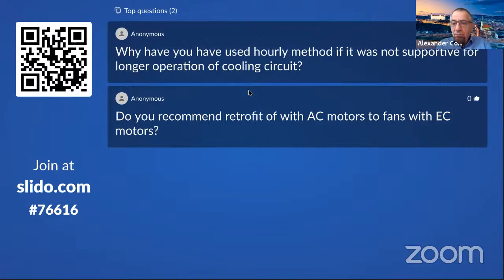Okay. The hourly method is a very promising method, and it should be used for calculating building heat demands, mostly where heat pumps and photovoltaic panels are installed, because the heat demands are calculated more precisely and we calculate less energy demand. It means that the building will be shifted to a better energy class, among nearly zero energy buildings.